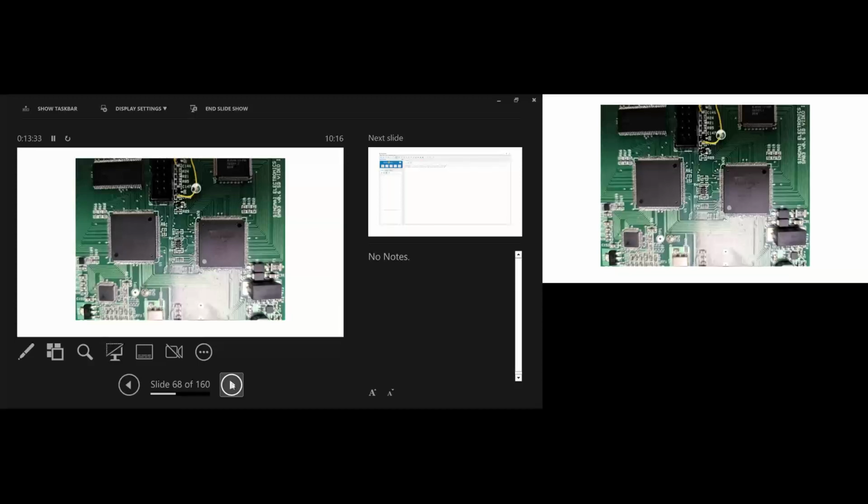This is because I don't like to use FPGA packages, because we like to hand solder and hand inspect. So we used the largest device that we could use in a LQFP package or something like that, but still had to use 2 devices. That, of course, meant we had to split the design in some way, and it didn't really split in a good way, but anyway, we managed it. The board was designed, now we were going to switch it on. Next slide, please.